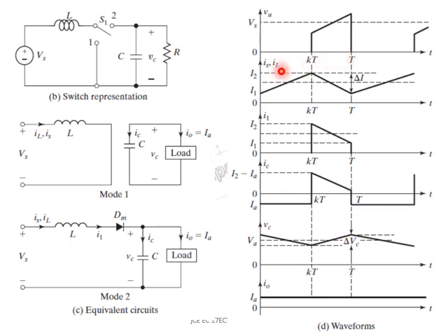During that time the voltage is going to rise from a low value to almost beyond Vs, because this additional voltage beyond Vs comes from the energy stored in the inductor. The voltage stored in the inductor and the source come in series, and the load voltage will be higher than Vs. That's why we say it's a step up chopper.